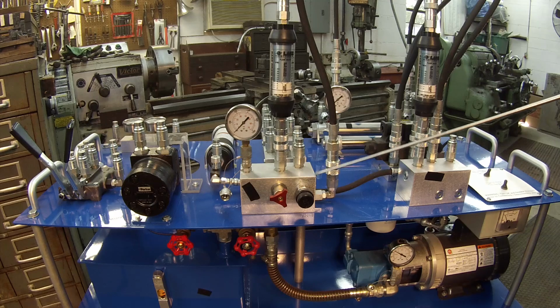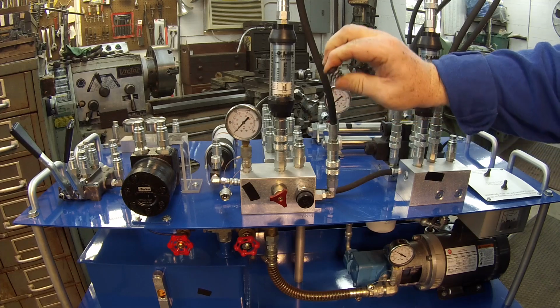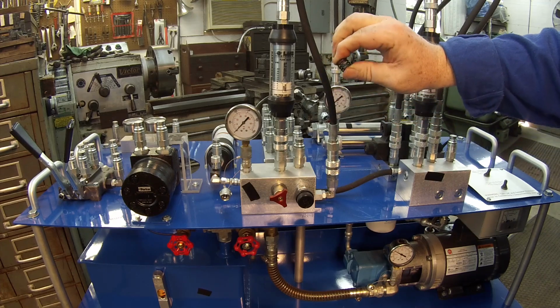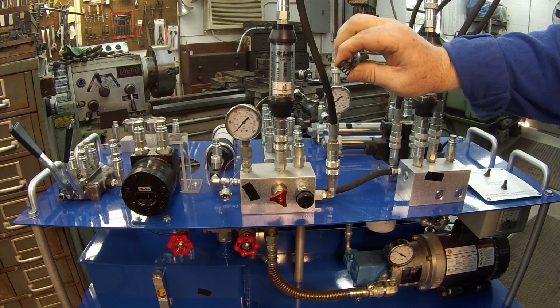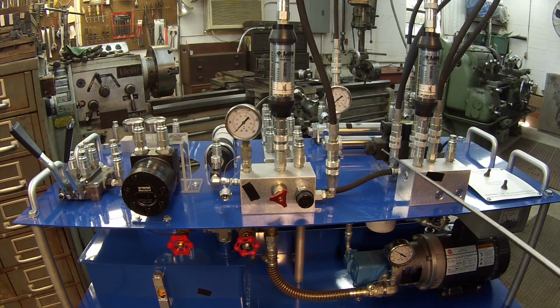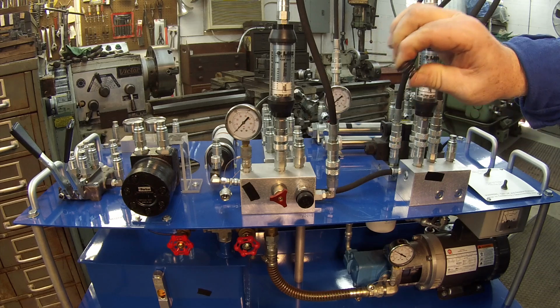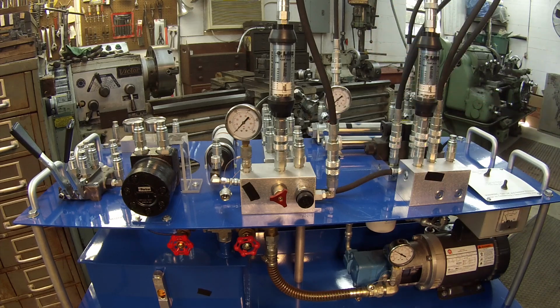The next one is any mechanical device. You have springs inside these mechanical devices, like your relief valve, that go back and forth every day. So with that mechanical motion, over some period of time, that is going to break. A relief valve, over a period of time, as it opens and closes, and your directional valve here, as it moves back and forth, those springs over a period of time are going to break. So just expect that.